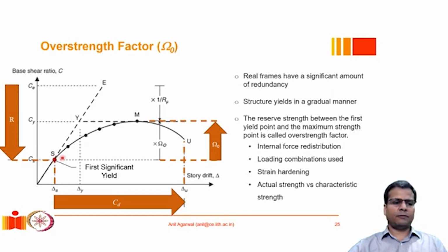And then in the previous example, we had assumed that the response is like this, like a straight line. But that was okay for a linearly elastic, perfectly plastic type of model. But most structural systems have quite a bit of strain hardening. This strain hardening could be the material level strain hardening. It could be because of the M-Phi curve, even for elastic plastic material properties. The moment curvature curve itself has some level of gradual increase in the moment until the entire cross-section plasticizes.